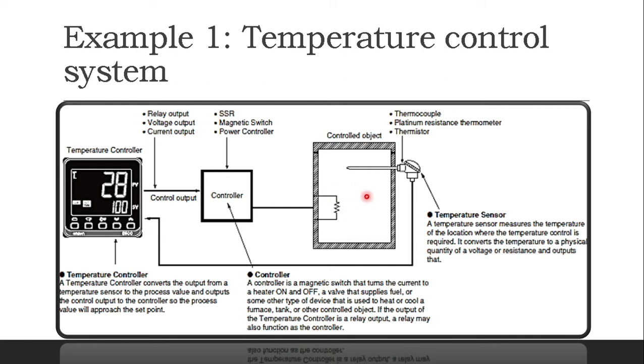So again, the desired temperature can be achieved using this thermometer. Again, we are going to check whether our programmed temperature and actual temperature are at the same level or not. If it is not the same level, again the controller will generate some signal and feed it to the electric furnace or heater. It is going to change the temperature. Okay, so this is a closed loop control system of temperature control. Using this, we can control the temperature of the system.